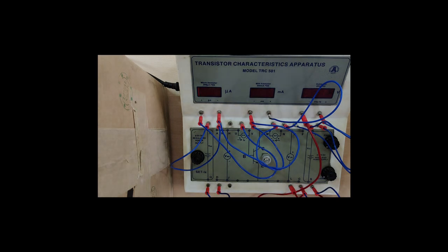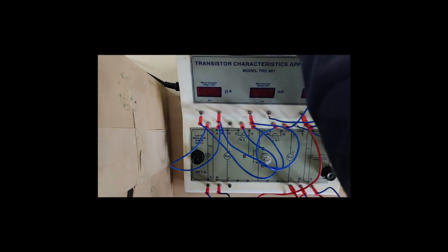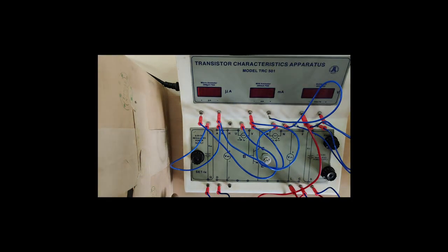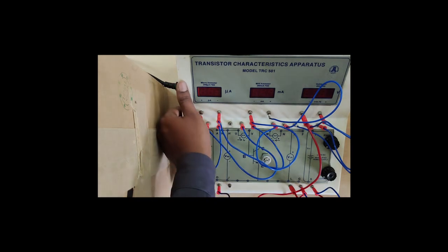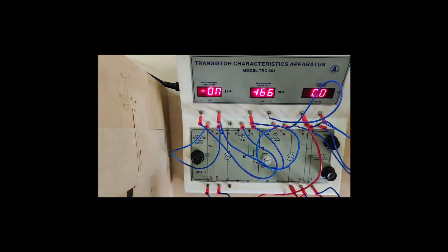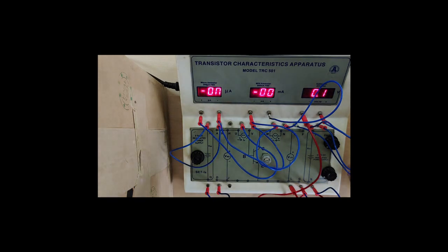First let us turn on the power supply and set the output voltage to a particular value. You have fine and coarse adjustments over here.